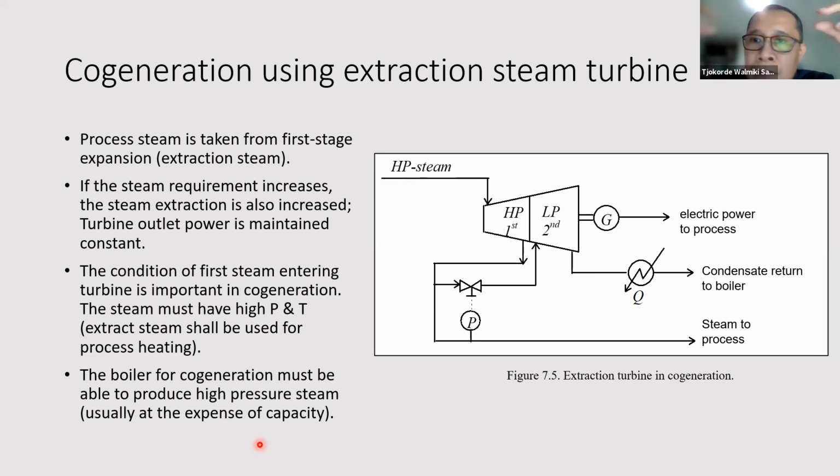But in the steam header itself, the steam condition has to be superheated. Otherwise, it will cause corrosion, water hammer, and all kinds of nasty things in terms of materials of construction and also fluid mechanics. So you have to increase the temperature a little bit more. If this is your process target temperature, this is your saturation steam temperature, right? And then your superheated steam temperature, aka your steam header temperature, has to be even further higher, to ensure there's a good degree of superheat. So that's how you design a steam system.